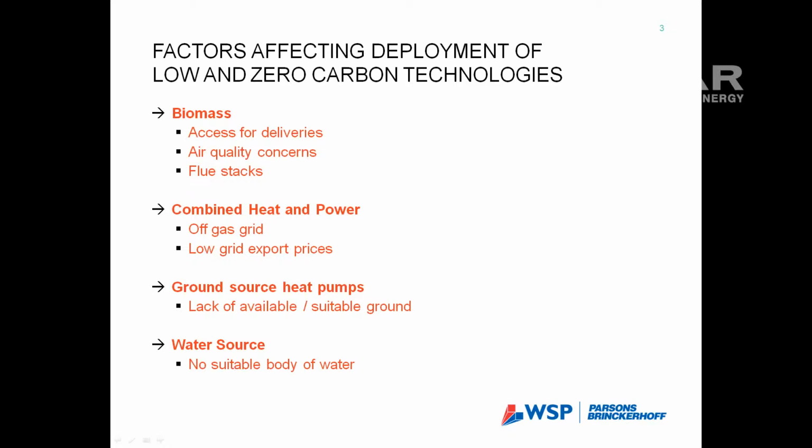Gas engine combined heat and power obviously only works if you've got a gas supply. The other problem in a residential scheme is you can't make use of the electricity from the gas engine directly for consumers, so it has to be exported, and you get a low export value, which can impact the scheme economics.